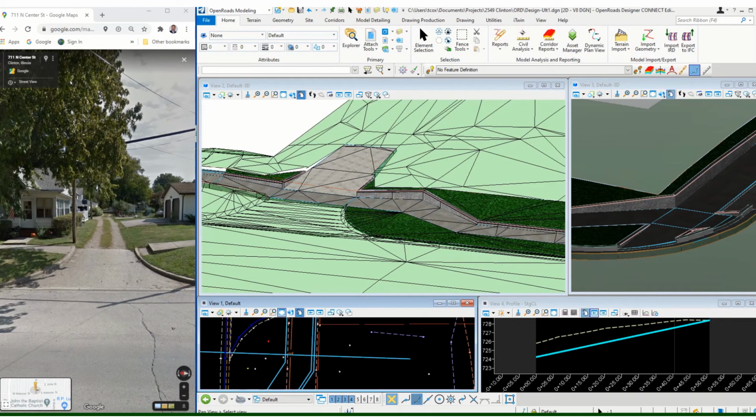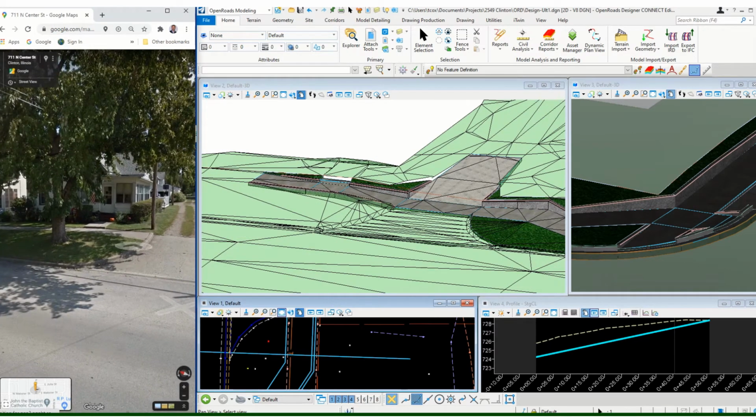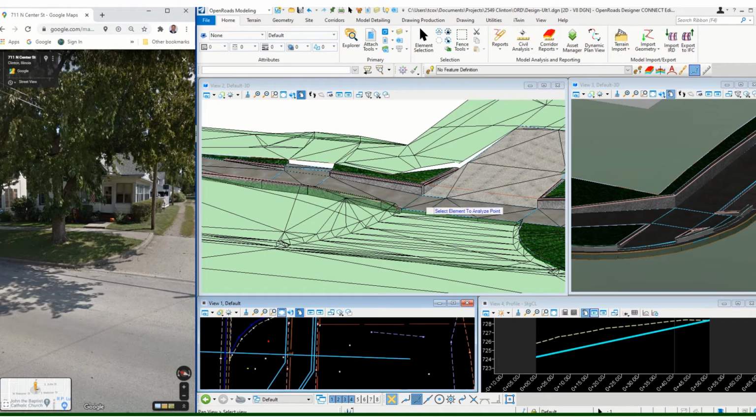Okay, now let's look at the other side of the alley. And here we need to get connected into this sidewalk that goes into this residence, that door right there. And so again, a maximum 8.33%, so connect the dots, so to speak.